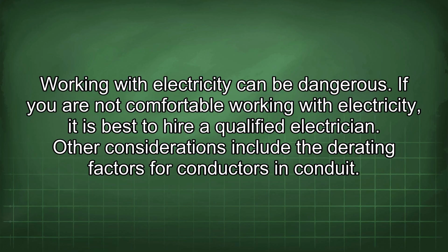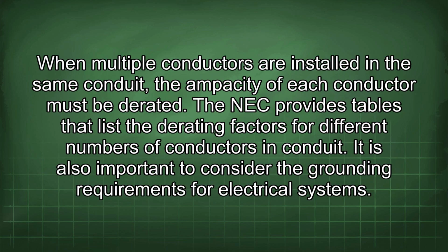Other considerations include the derating factors for conductors in conduit. When multiple conductors are installed in the same conduit, the ampacity of each conductor must be derated. The NEC provides tables that list the derating factors for different numbers of conductors in conduit.